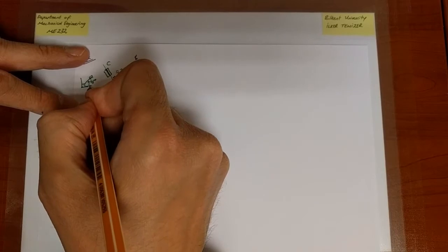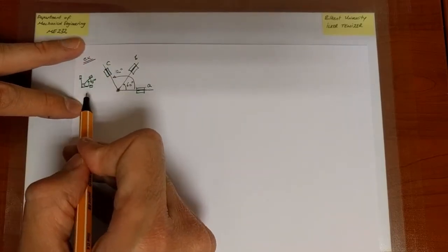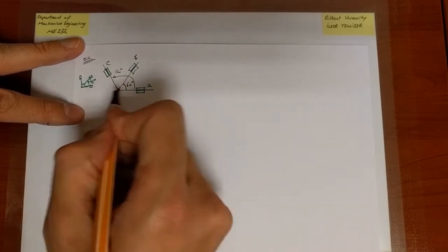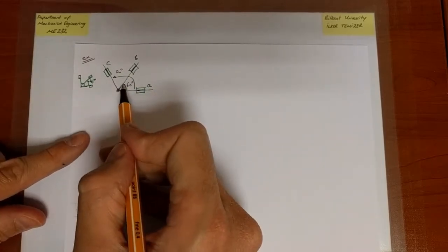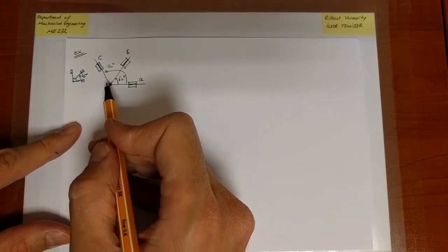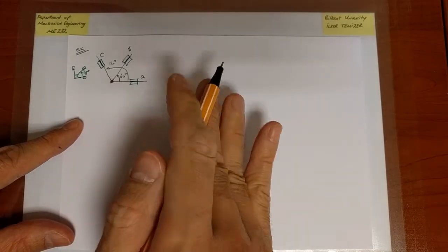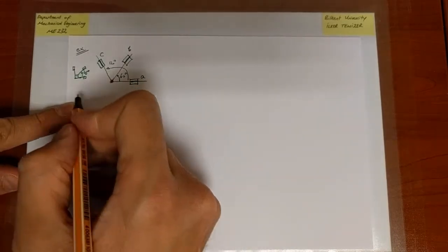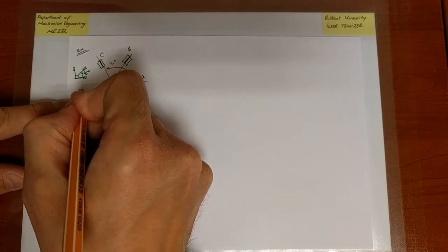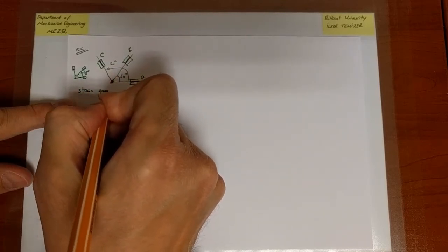So this would be an alternative choice of 3 strain gauges. Either way, it will be sufficient. What's important is I have 3, and they work in a special manner, the way they are oriented, to deliver me the information that I need. Either way, this combination of 3 is typically called a strain gauge rosette.